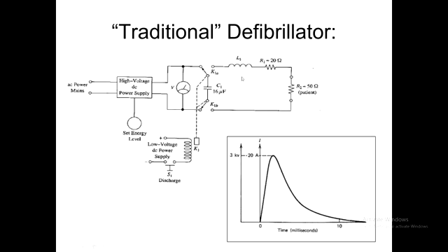The rationale for having the inductor present there is to make a damped circuit with a little bit of oscillation to it, but not much. And the whole idea about that is to dump the energy as quickly as is needed, but not too quickly, so that we don't end up re-stimulating within the vulnerable period where the cardiac cycle has resumed.